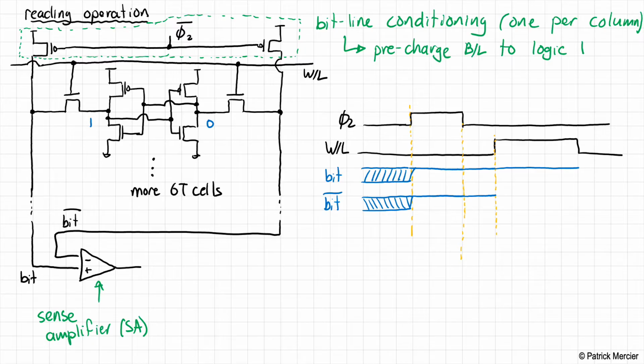Okay, so even though it's a small transistor and there happens to be a lot of capacitance on the bit line, it will slowly charge down. Okay, and then eventually it'll level out after the word line stops. So after a certain period of time, we're going to have a differential voltage derived or achieved between bit and bit bar. So let's write down a few observations here.